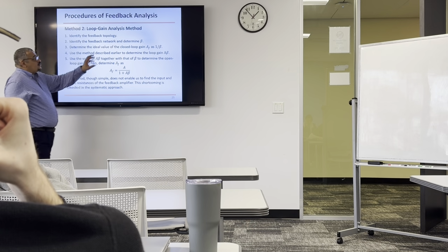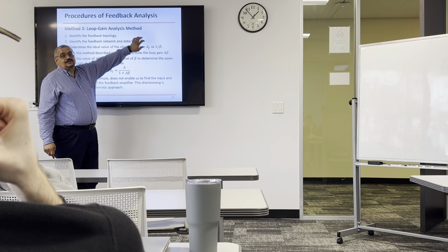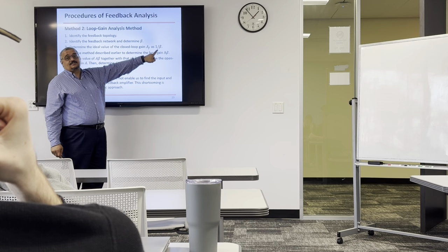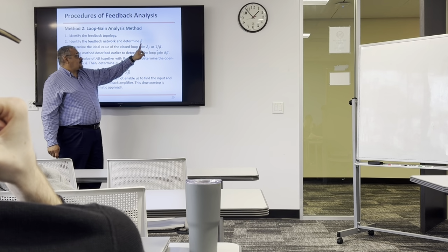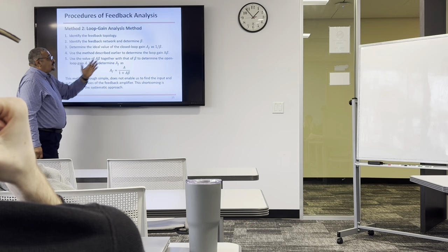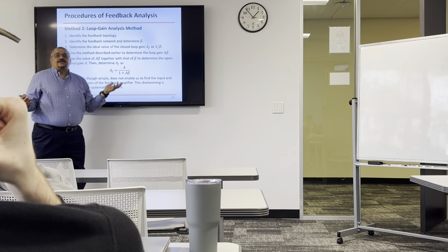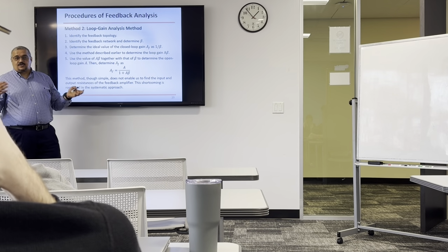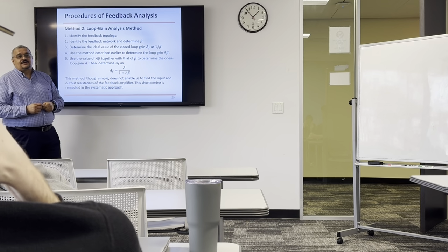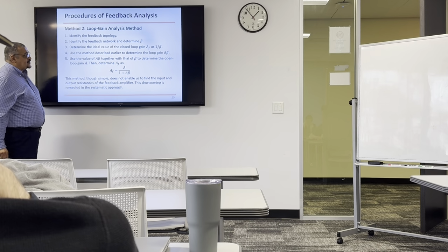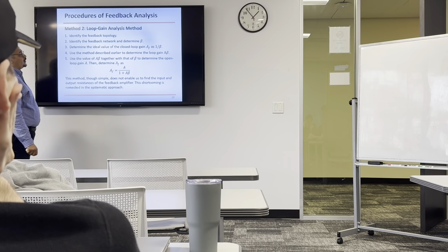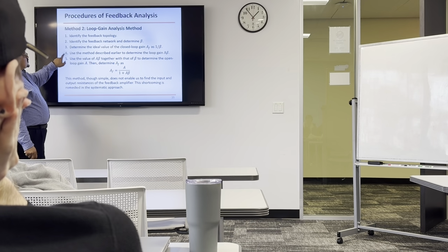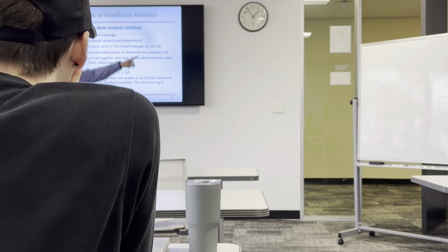First, it gives you the ideal negative feedback gain. The negative feedback gain ideally is going to be 1, the reciprocal of this value. So if you find beta 0.1, meaning that the ideal amplification is going to be 10. 0.01, then the ideal feedback gain is going to be 1 over 0.01, which is 100. Then use the method of finding the loop gain.